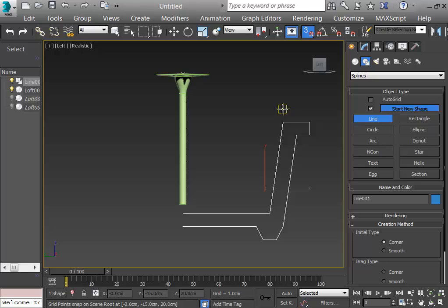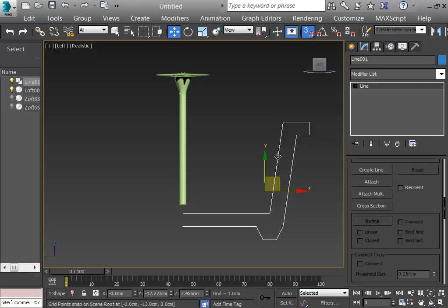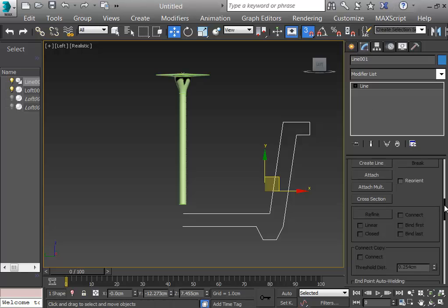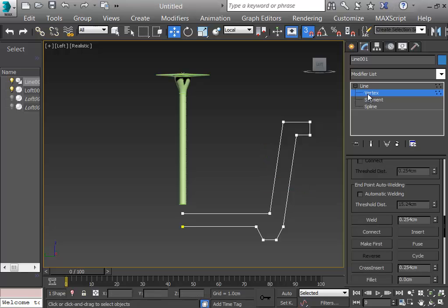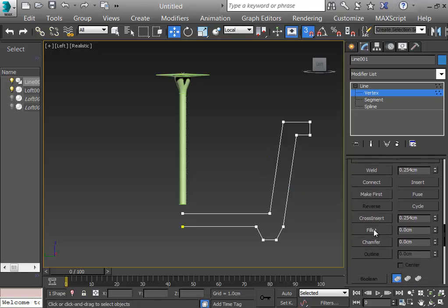So what I will do, I'm just disabled the grid lines by Ctrl G, and I select the line in the modify section. I scroll down here. Okay, I should select the vertexes, and when I select the vertexes, sorry, not define the flat. I select the flat now. I have select these all sides. Then I am now flattening them. Okay, and I will flat these sides slightly, not too much. Okay, but what I observe that is so thick, I want it to make a little bit narrower. So I select the vertexes, I disable the flat, and by W, I hit the W.